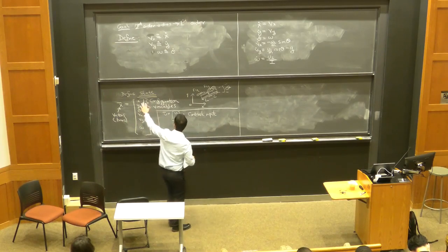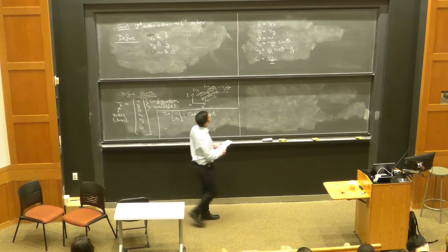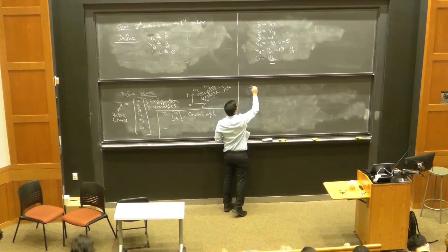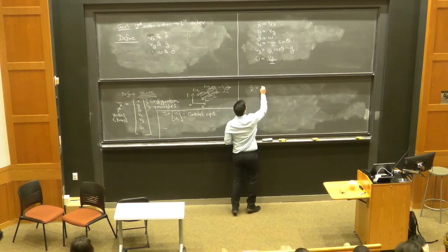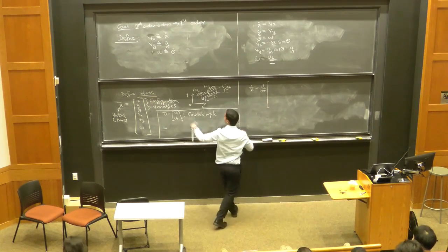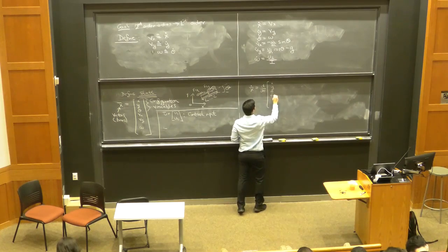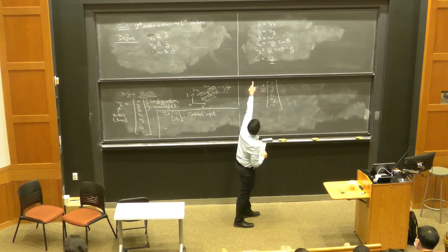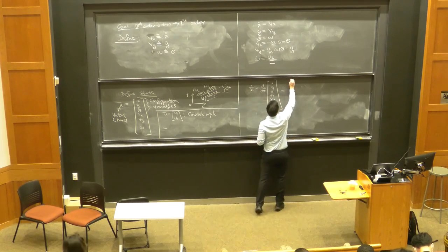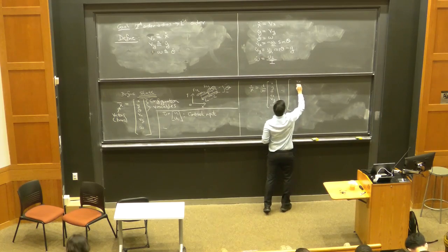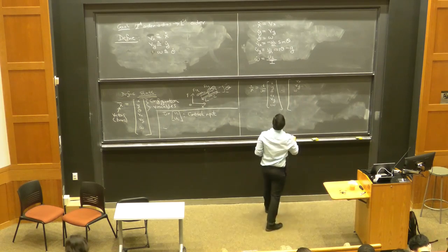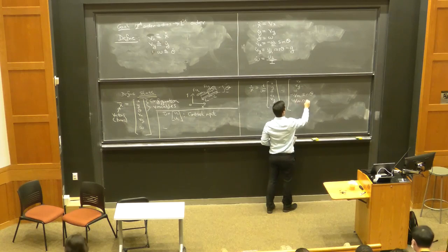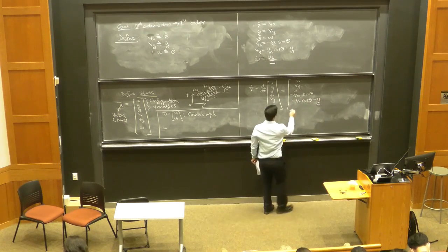Okay, so with this introduction of the state and the control input, we can rewrite these first order differential equations. Let me do that in the following form. x dot, the time derivative of the state, which is by definition d over dt of x, which I defined over here as y, theta, vx, vy, omega. The time derivative of the state is the right-hand side of these equations. Just copy that over: Vx, Vy, omega, and minus U1 over m sine theta, U1 over m cosine theta minus g, and then U2 over I.